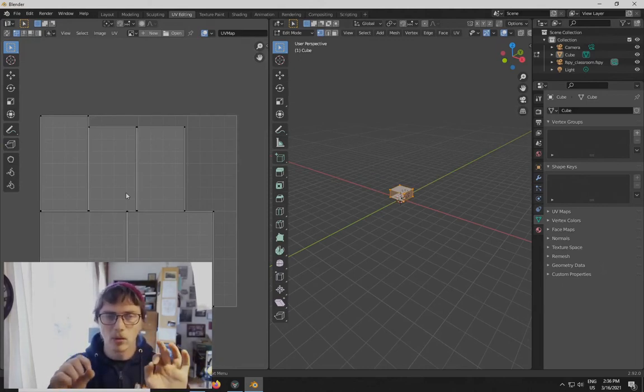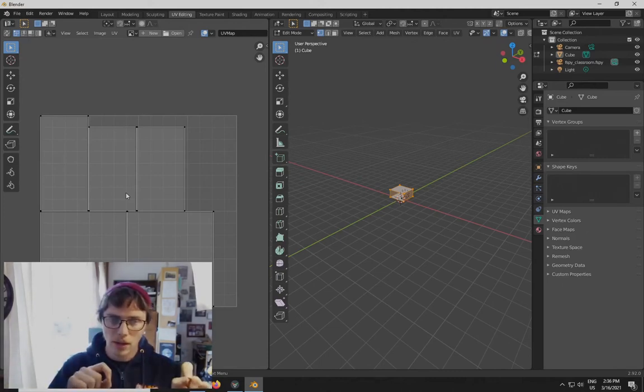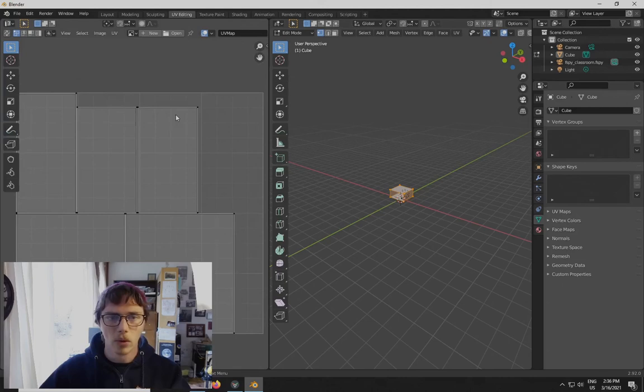Specifically UV unwrapping, what's great about what I'm showing you is that as long as you have a UV unwrapping, this will work, and you don't have to do project from view. Whereas the old method requires you to have a specific UV unwrapping, this will use whatever UV unwrapping you have. In this case, it's convenient that we have island margins, but you can use whatever UV unwrapping you've got.